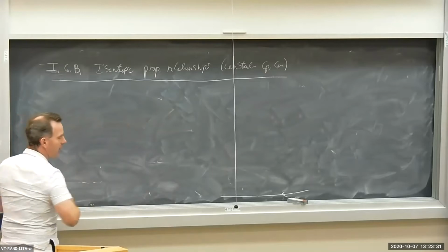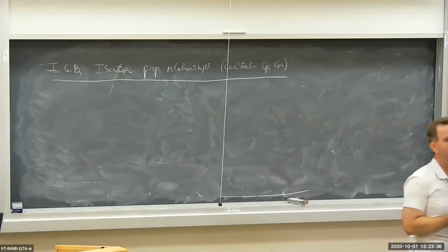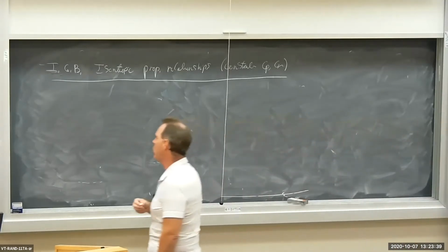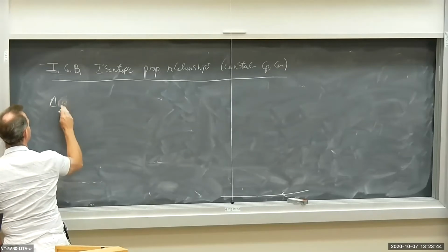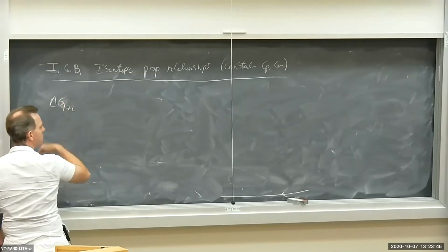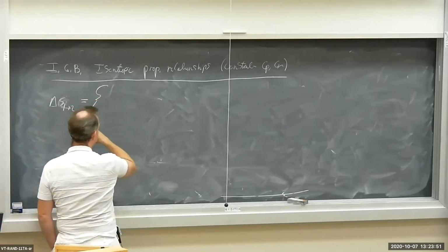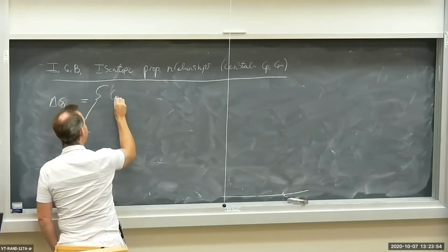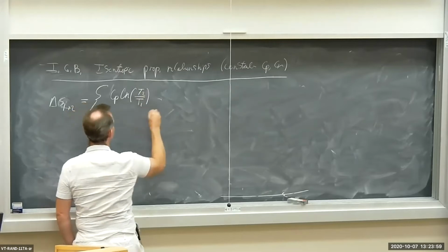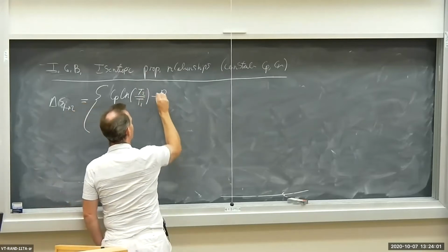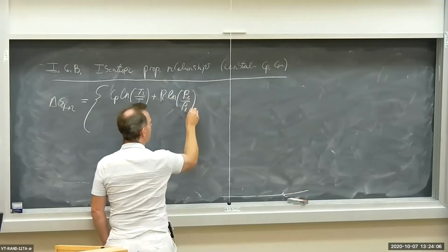Okay, so we previously had two equations that were valid for an overall process, ideal gas behavior, constant specific heats. As you recall, we had two equations. We had delta S, or the change in specific entropy from state 1 to state 2, equal to two expressions. I had Cp ln T2 over T1 plus R ln P2 over P1. Okay, that was one expression.